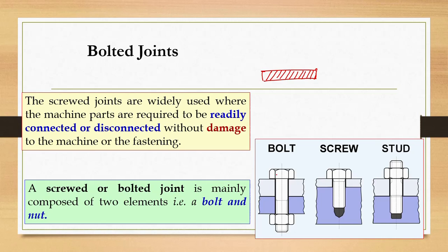The bolts also have three main characteristics, or you can say three main shapes. They are all threaded joints, but if you have a head, generally it's a hexagonal head. It's not necessarily hexagonal; it can be a square head, but generally the bolts available in the market have a hexagonal head. The shape of the head looks like this.